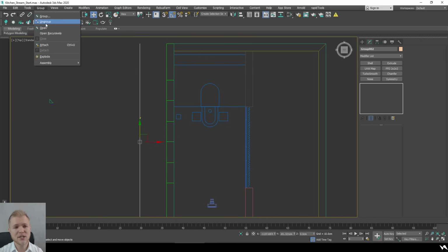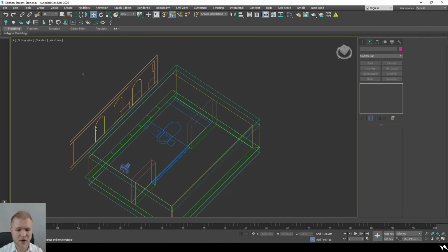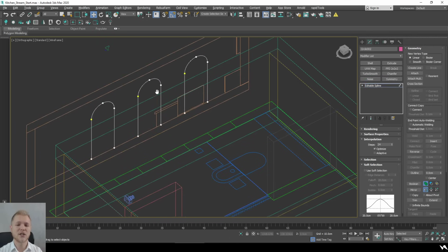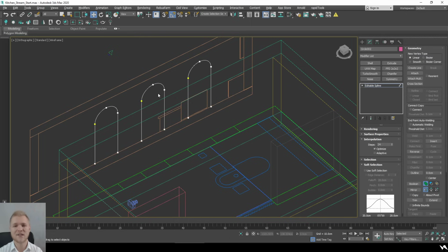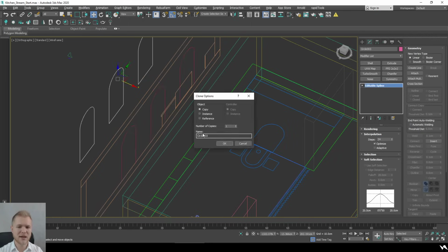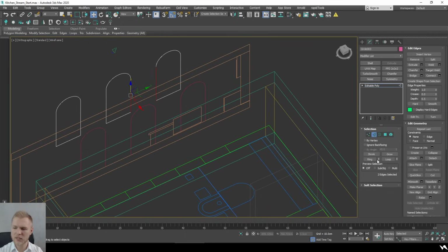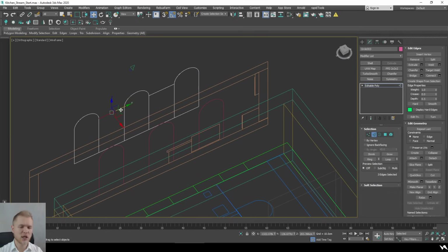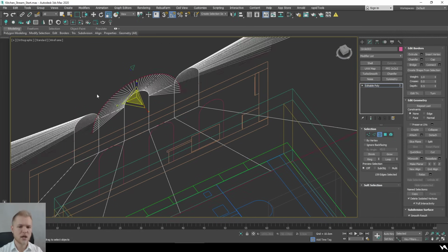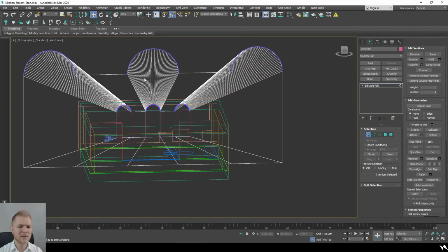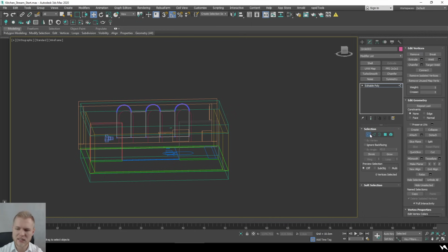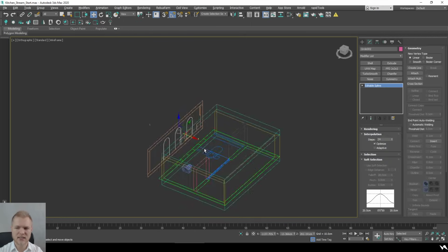As you can see now, I'm just ungrouping these files, because honestly, you could create arches by simply going ahead and doing this by editable poly and making sure that each element of your mesh is just perfect. But honestly, it's a waste of time, because before you actually finish welding and bridging all those elements like I do right now, you could basically just create a shape and be done with it in a second. So this is not really going to be a perfect solution. So we're just going to delete this and try to work with it as a spline.